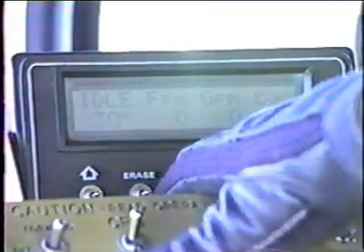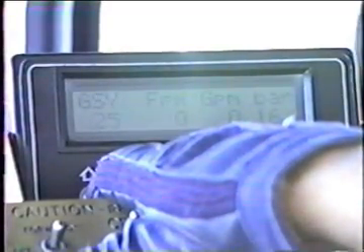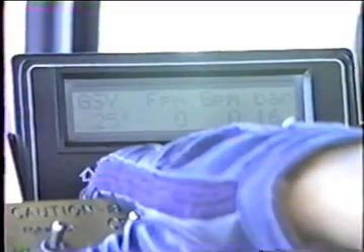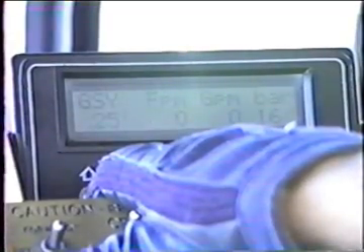If we push the second switch up to the erase position, that'll change to GSY, gallons per square yard. If we do it again, it goes back to idle. Do it again, it goes back to GSY. It just ratchets over twice there. Okay, gallons per square yard. There's the spread rate again. And right now it is telling us that it is ready to spread 0.25 gallons per square yard.